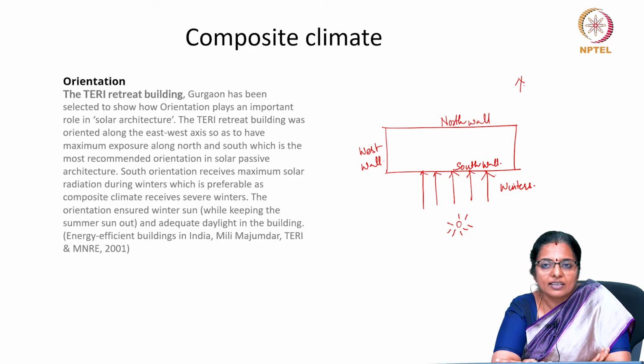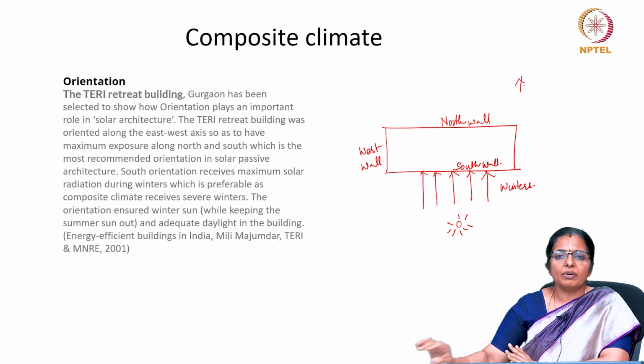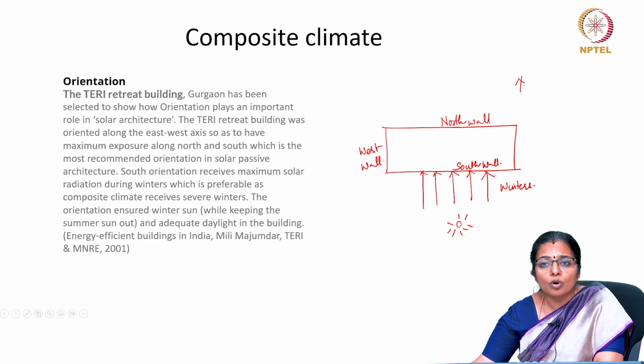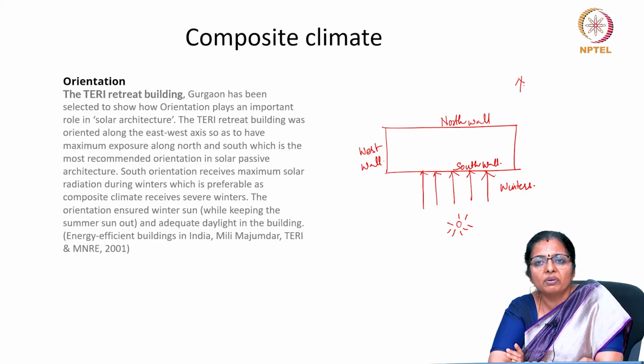In upland areas, heating in winter becomes more important than cooling in summer. Hence, rather compact structures with minimal but proper sun oriented exterior surfaces are desirable. Buildings may be large and grouped close together. Row houses or adjoining buildings have the advantage of reduced heat loss. Courtyard buildings with proper wind protection are a suitable solution.